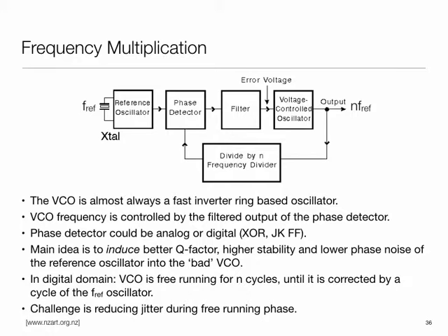Usually, again, on microcontrollers, you would find that there would be a pretty elaborate clocking block, and it's going to take as the reference either a ring oscillator, which is used in early stages of the system putting up, or an external crystal oscillator, and then it would have the ability to generate multiple frequencies, some frequencies meant for the processor to operate at, some for things like the USB bus or a radio, which all have unique requirements. And the magic happens because of the PLLs.